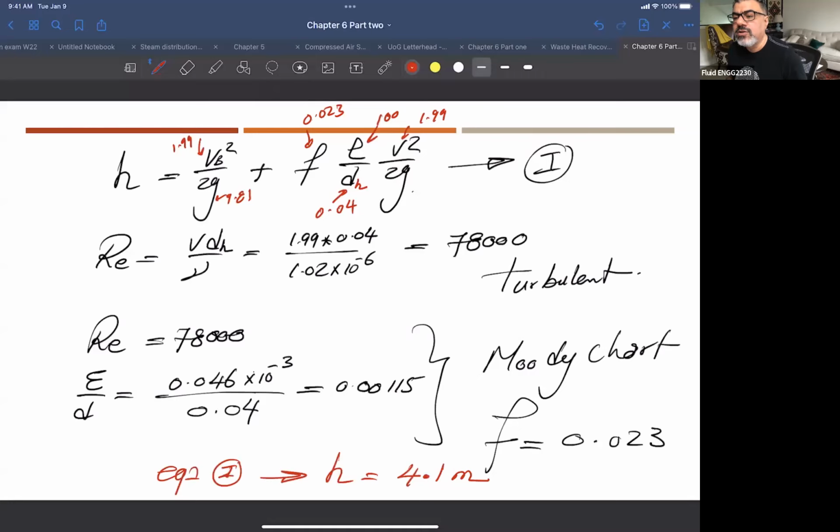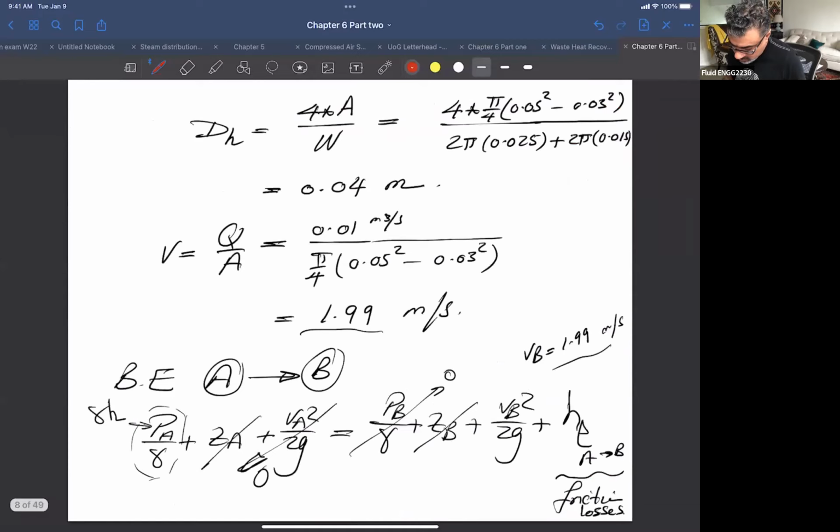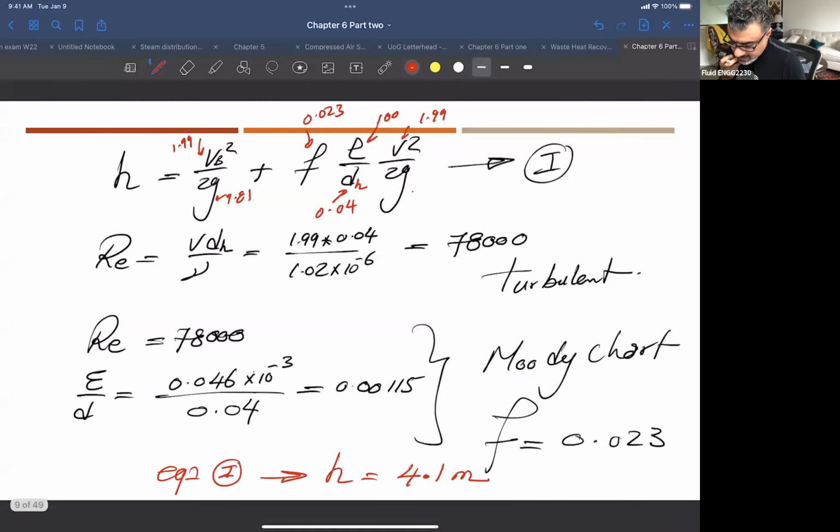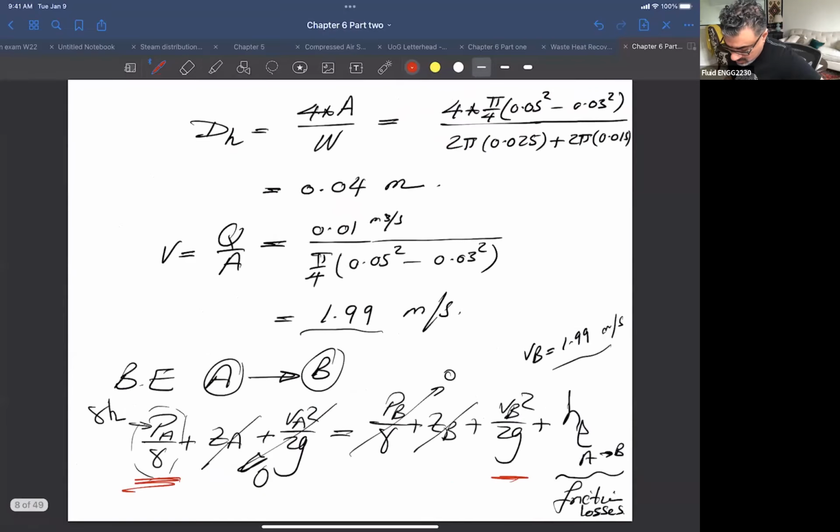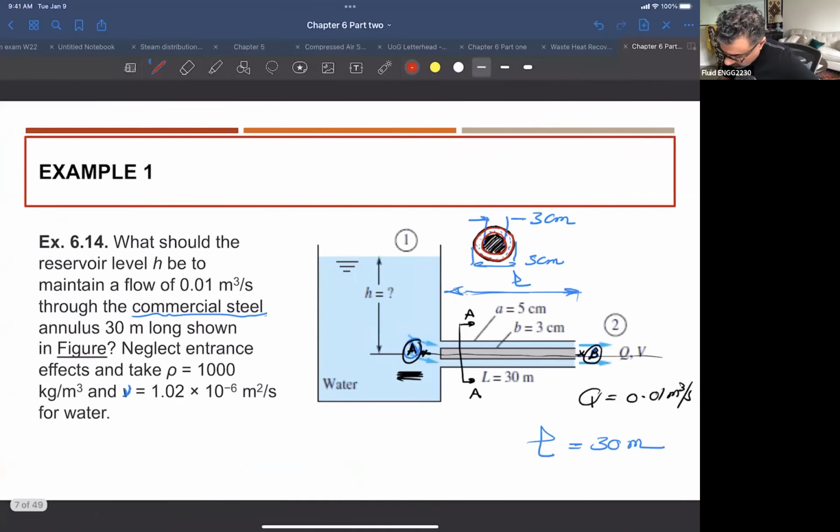Yeah, we didn't rearrange that much. We just put the equation and now we have H here and the velocity here plus this. So basically, that's whatever is left from the Bernoulli equation. Epsilon is, remember, every time we solve the problem, we try to find the material roughness, right? The material roughness, from last week's lectures, is listed in tables.